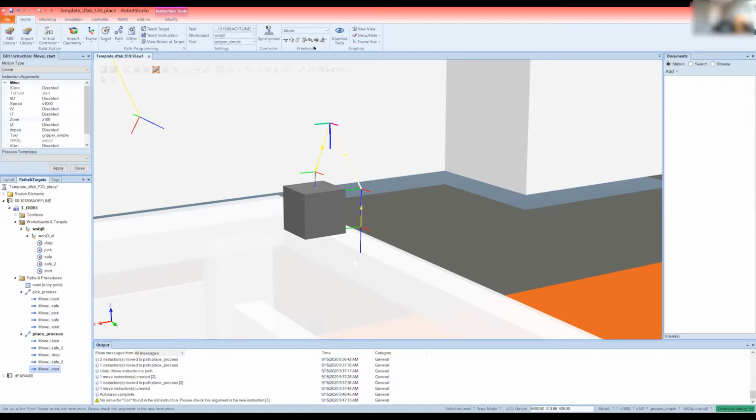Just to clarify one more time. Essentially, the Z value, or the zone value, is basically defining how close you get to a particular point, and then Move L and Move J are the vector that gets to the point, if I'm correct. Okay, so I think you're completely correct about the Z value. The Z value just defines that distance. So basically, it says how close the robot gets to the target. That's the correct one.